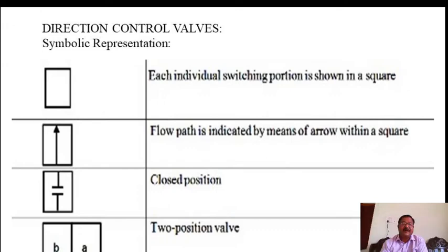Otherwise, if the hydraulic components are represented by their own symbols, then all people who know hydraulic systems can identify what type of valve is adopted in the circuit. So understanding the symbolic representation of hydraulic components is very essential while designing the hydraulic circuit.